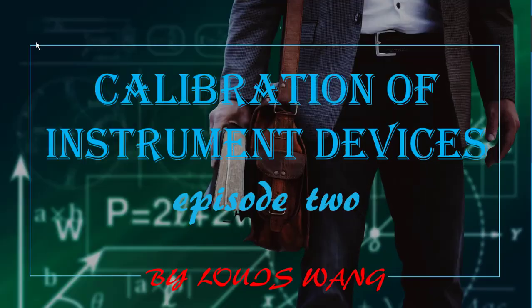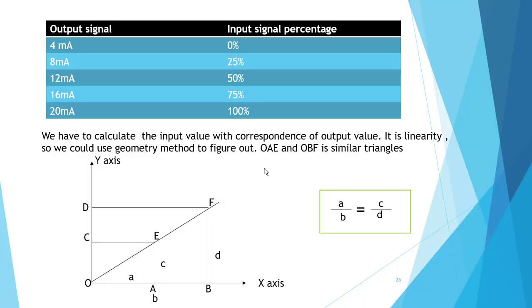Hi, today we continue to talk about calibration of instrumentation devices. If you want to do calibration, you should remember some numbers. For the output signal, most of the time we use 4 to 20 mA, but you should remember 4 mA equals 0%, 8 mA equals 25%, 12 mA is 50%, 16 is 75%, 20 mA is 100%. If you do calibration, you have to calculate.